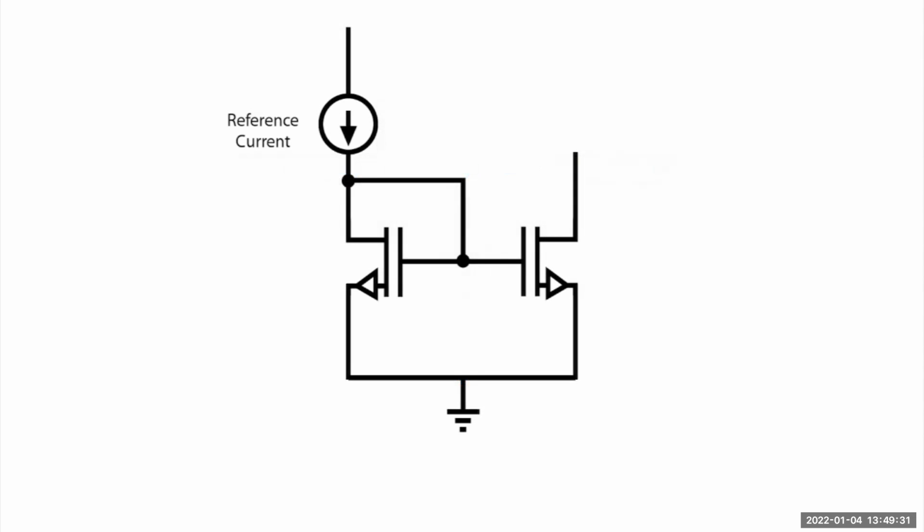At the reference transistor, the drain current is equivalent to the reference current because a field effect transistor does not draw any current through its gate. This means that the output current of a MOS current source will be closer to the reference current than a circuit that implements BJTs with a finite beta. Both of the FETs are operating in saturation mode. This means that there is a constant potential applied across them. The drain current of a MOSFET is a function of both gate source voltage and the gate drain voltage.